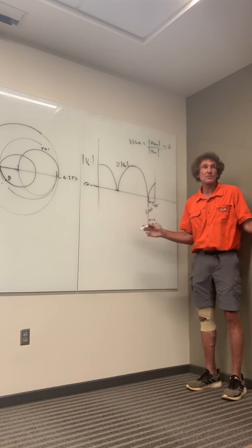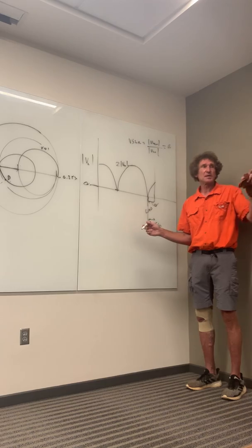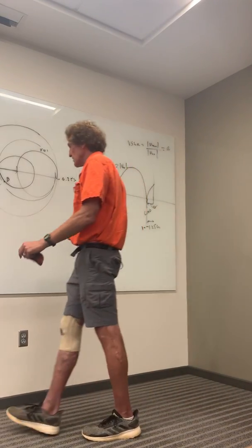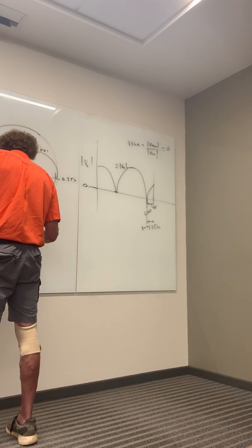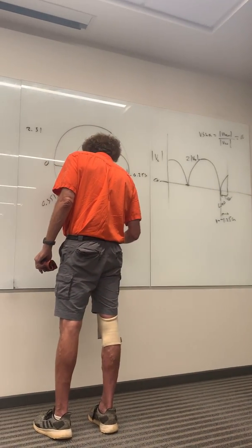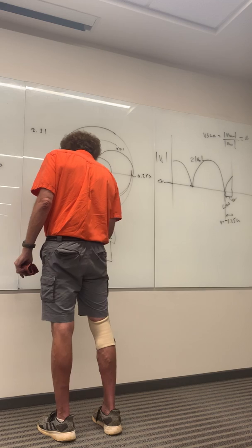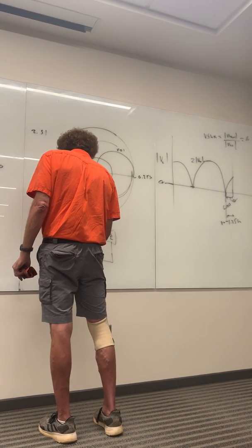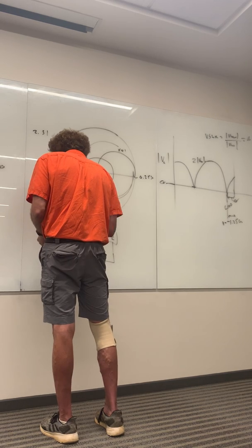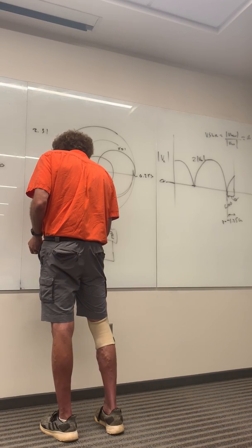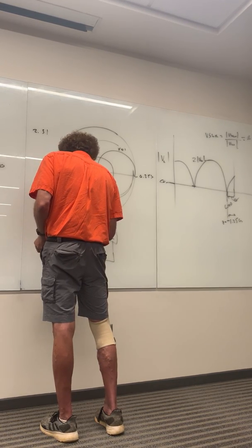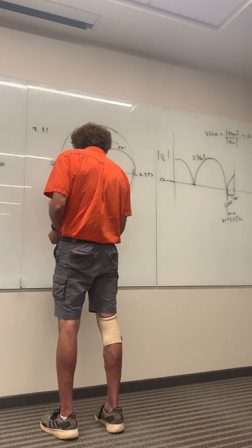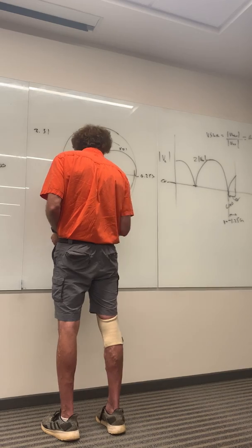Oh, by the way, here's how we get the wavelength. Is the velocity c on there? It doesn't say. Then we have to assume that the velocity on the transmission line, like here, where this is ZL, and this is Z naught. If it doesn't say different, or unless there's a better reason for it, then you have to assume, is it 50 ohms for this one or 100? 50. 50? All right, you have to assume phase velocity is going to be C.